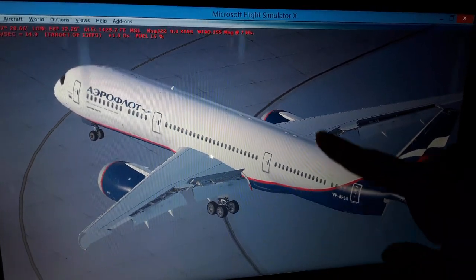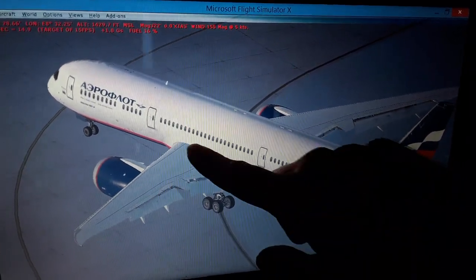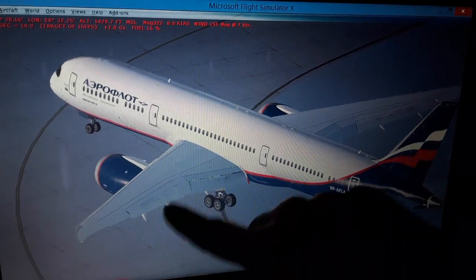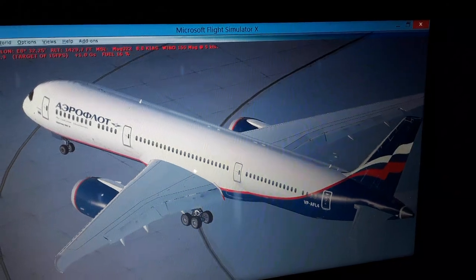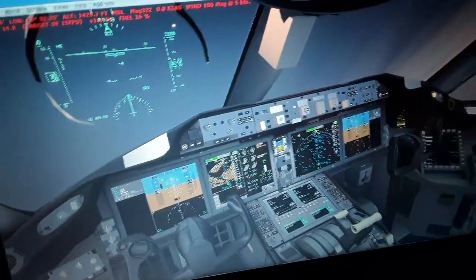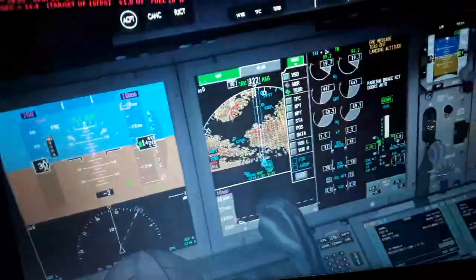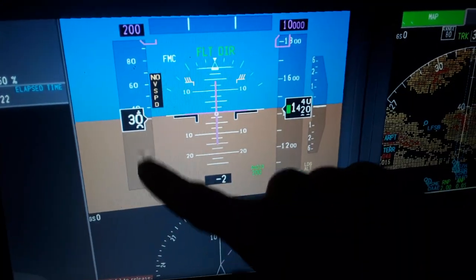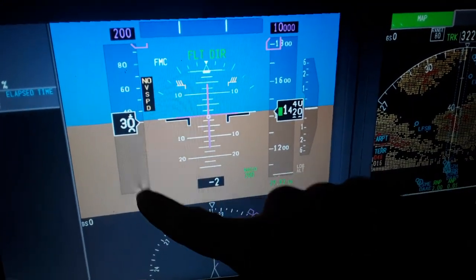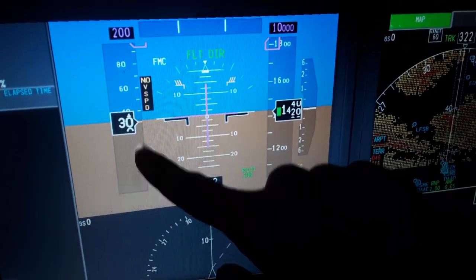Also where the stall will begin, the airflow becomes detached from the top surface of the wings all the way back. And now the wings stall, so we need to monitor here inside the aircraft all the time when we fly the airspeed indicated, the airspeed table over here. You have the stall speed just below the airspeed here with a red number or yellow color.